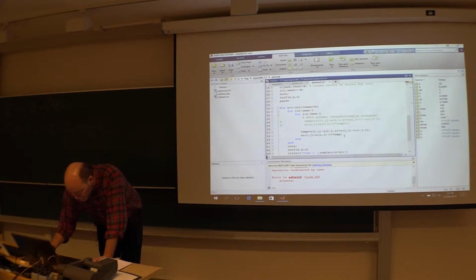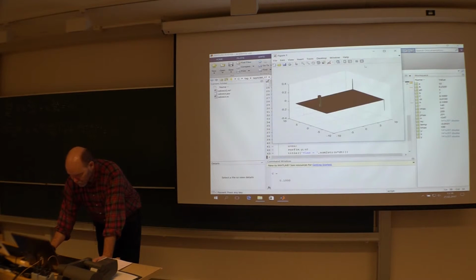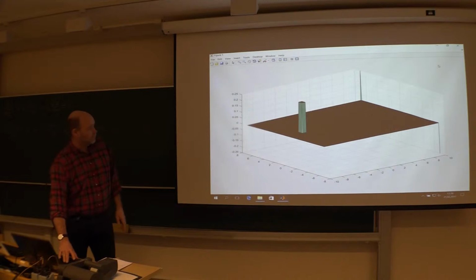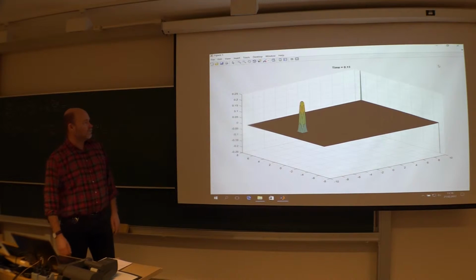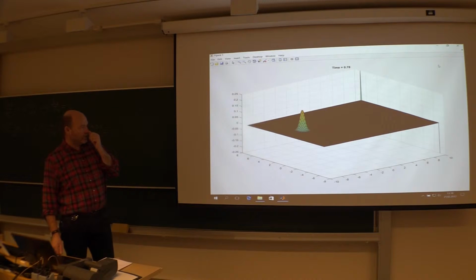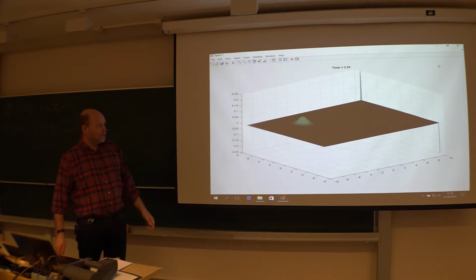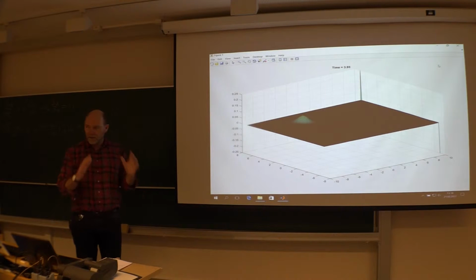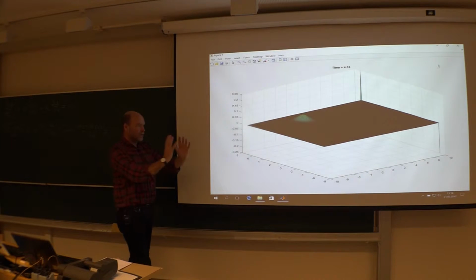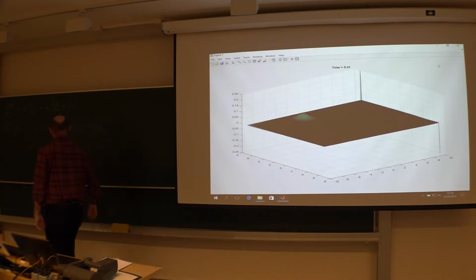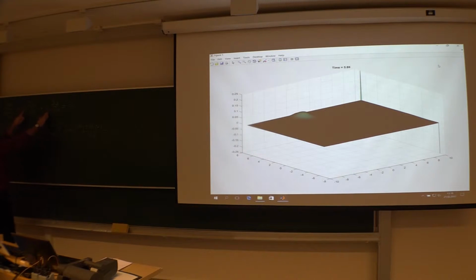Let's try that one. First order upwind. It doesn't explode, but it disappears. I mean, the solution for the problem is not like this. The initial disturbance should only be moved. It should be advected with a constant velocity. It shouldn't be distorted like this.